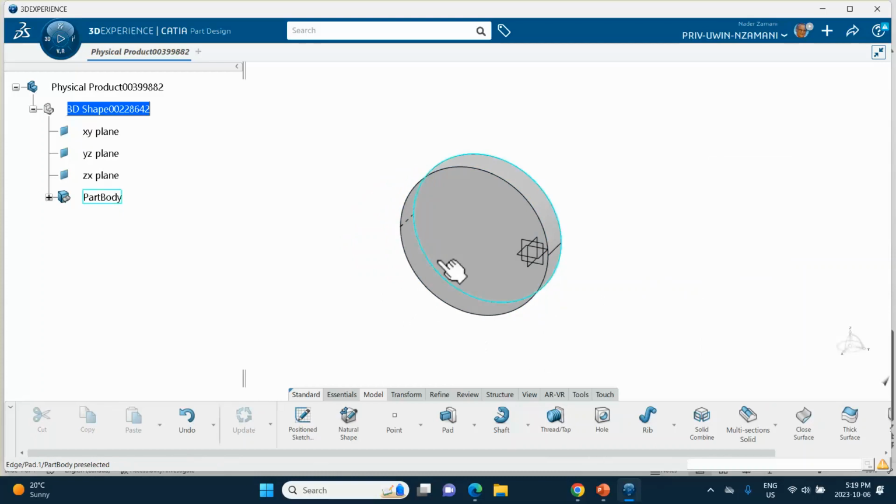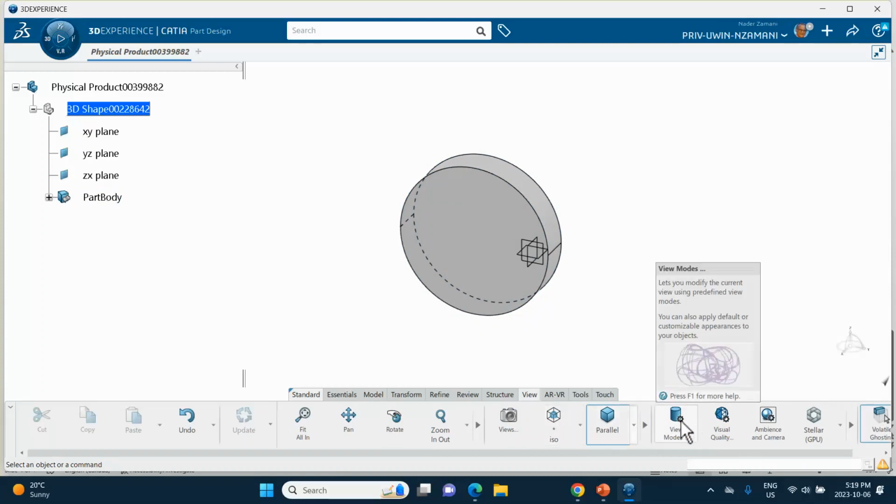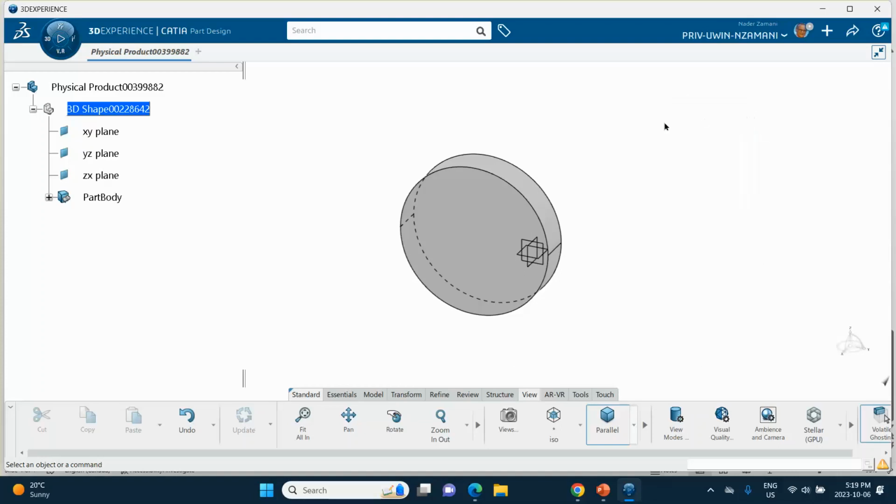I'm using the view so that it also shows you the hidden line. I'm sure you know how to deactivate this. In other words, you can go to view, and then you can go to display view modes. And then depending on what you want, you can deactivate that, but I want to be able to see those, which is right here. It's right there. Okay. Let's get rid of that.